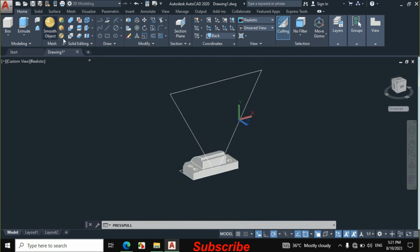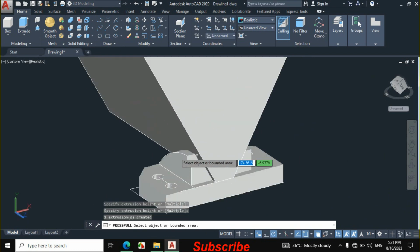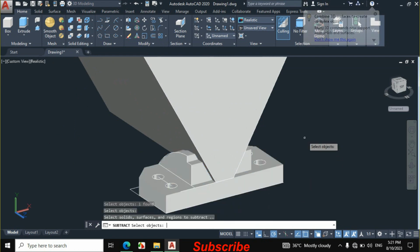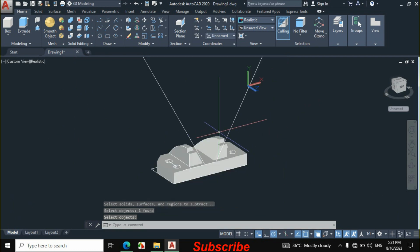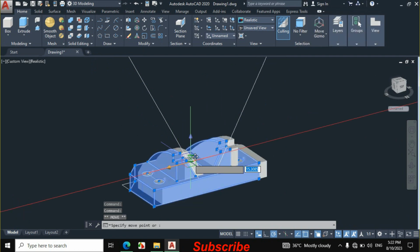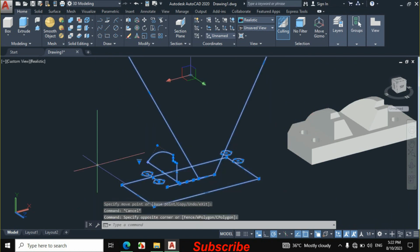Now click on press pull and press pull this towards this side. Press escape. Now click on solid subtract. First select this portion, the 3D solid, and then press enter. Then select this portion and press enter. Now click on solid union and select all this object, press enter. Now move this object towards this side and erase all these lines.